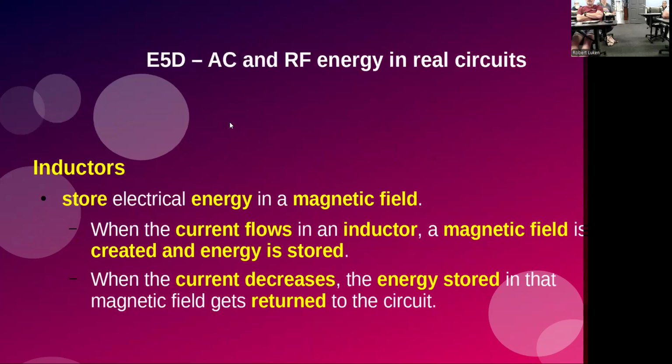Okay, if I have an inductor, we know that it stores energy in the magnetic field. Because it's typically in coil form, with turns wrapped around a toroid or in the air or whatever, you have parasitic capacitance between the windings, called interwinding capacitance. The closer those windings are together, the more the capacitance. As you spread it out, the capacitance decreases, but so does the inductance, because part of the inductance formula is how many turns, how close together they are, and what's the area inside.